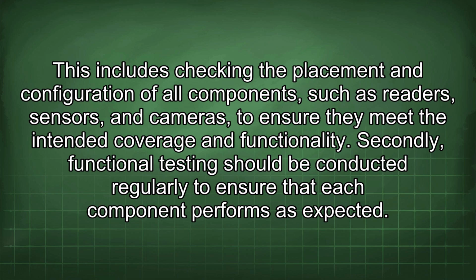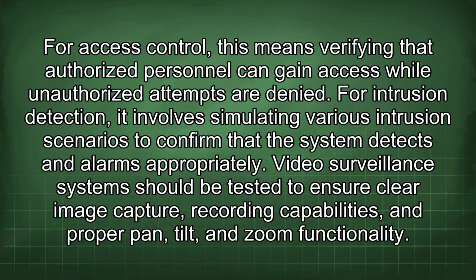Secondly, functional testing should be conducted regularly to ensure that each component performs as expected. For access control, this means verifying that authorized personnel can gain access while unauthorized attempts are denied. For intrusion detection, it involves simulating various intrusion scenarios to confirm that the system detects and alarms appropriately. Video surveillance systems should be tested to ensure clear image capture, recording capabilities, and proper pan, tilt, and zoom functionality.